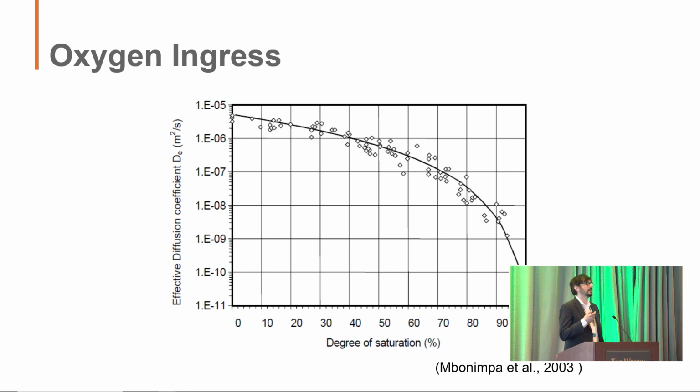So, I will say it once more. It is important to understand that all our plots and outputs will be regarding the degree of saturation, as we know that if it is high enough, we will consider an 80% threshold to see if the cover has a good performance. We will take a look at that so that we know if oxygen is ingressing or not to our system.